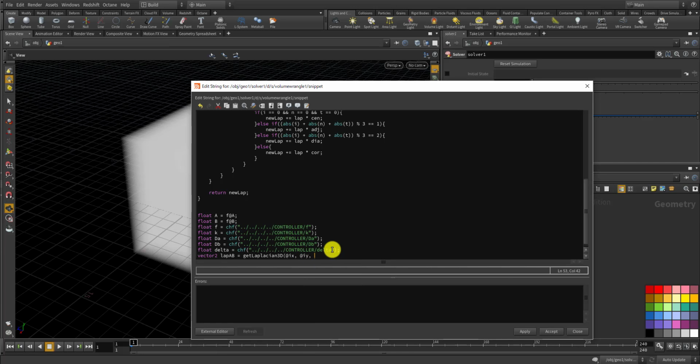Ix, Iy, Iz, which is the x and y and z index for the volume, each volume. And for the values, okay, well, the total, since I have to make all the values, if you add all the values together, it should be 0. So for the center, should be -1. And okay, for the adjacent, I could go like 0.2 divided by 2.8. And for the diagonal, 0.1 divided by 2.8. And for the corner, 0.05 divided by 2.8.